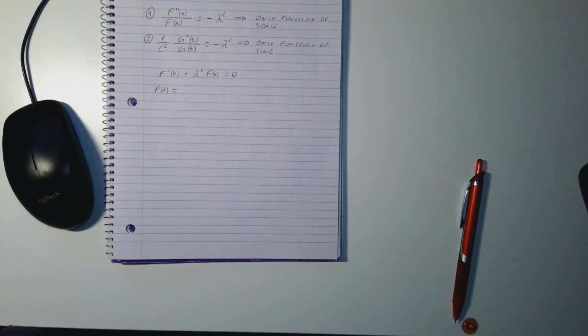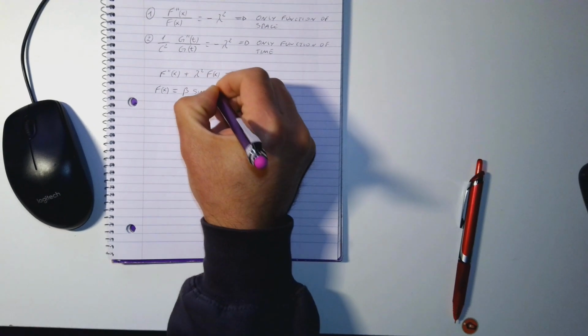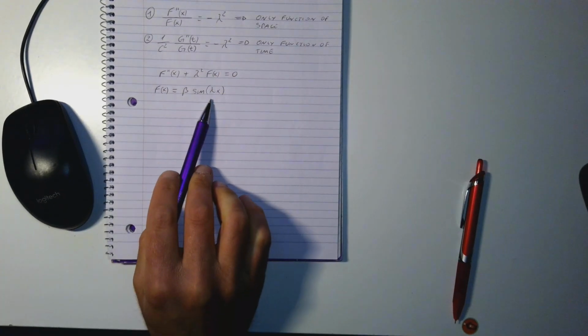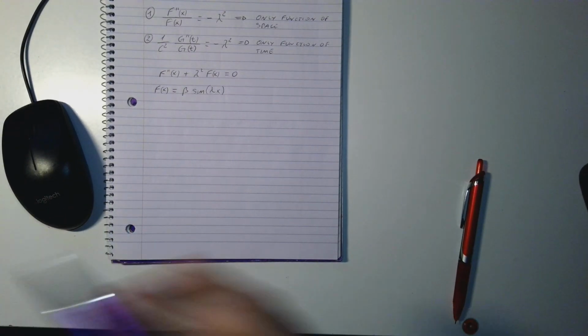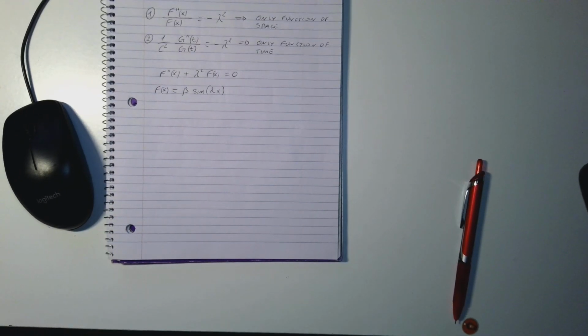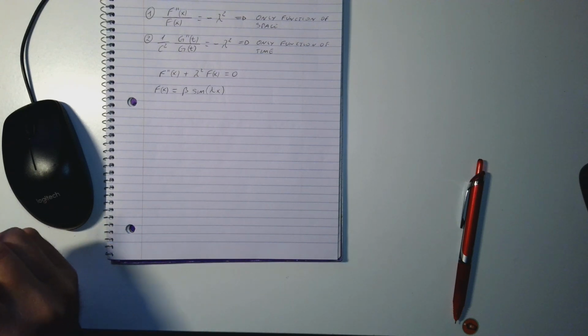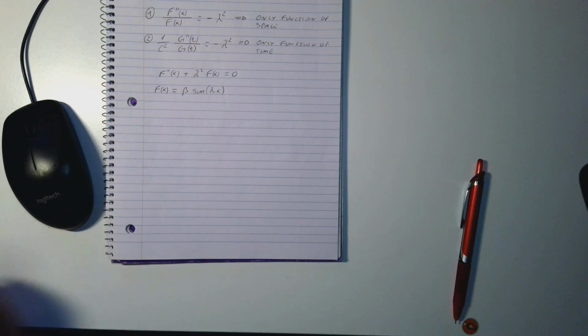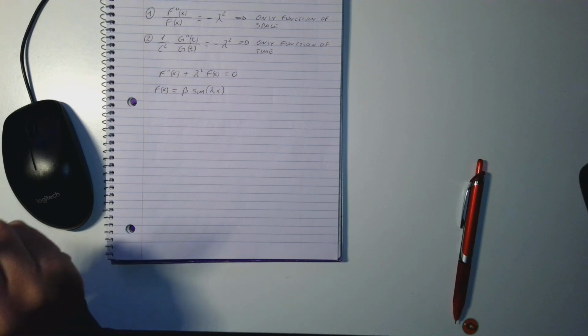We can use, for example, beta times sine of lambda x. Again, the solution of this equation is not only one solution. There are multiple functions that can satisfy this equation, considering the boundary conditions. As long as we have no displacement at the beginning and at the end, because of the boundary conditions, we need to have one sinusoidal function that has basically 0 and 0 at the beginning and at the end.